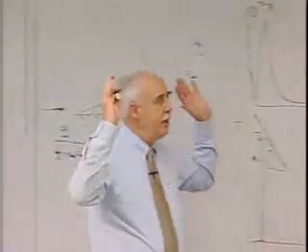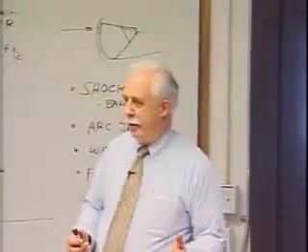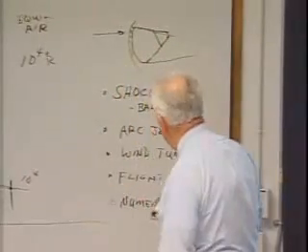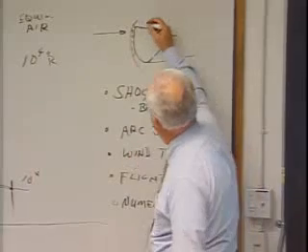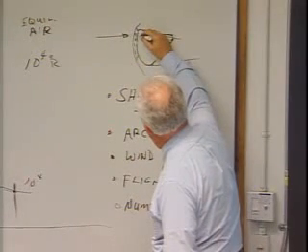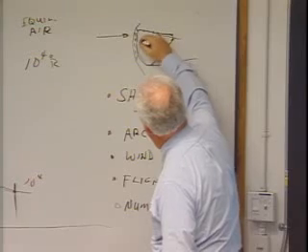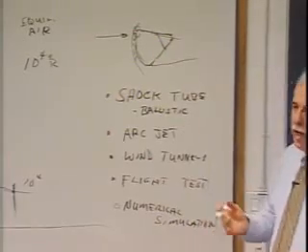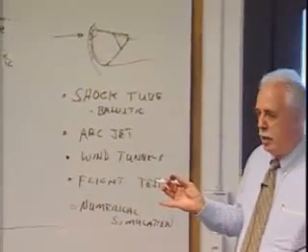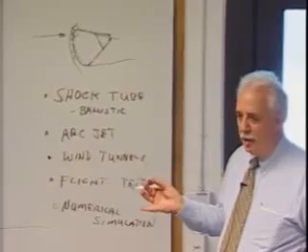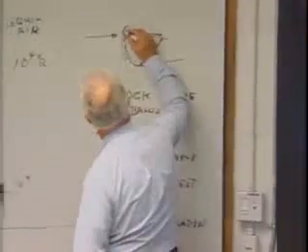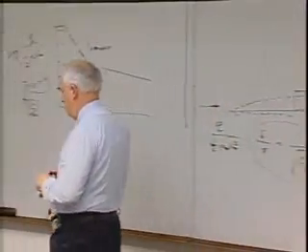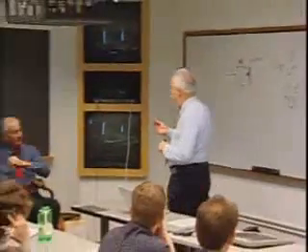Now, everybody tells us we were twice too heavy on the ablator on a capsule, and I'll explain that in a bit. It's a systems engineering problem. We got away from it on shuttle, so pay attention when I get to that problem. In any event, we were a factor of 2 high over most of the vehicle, but not in this region. In that region, we were right on. Not by knowing what we were doing, just by luck, okay? So when you say right on, what you're saying is that the char layer went essentially all the way in... We hit our temperature requirement on the structure.